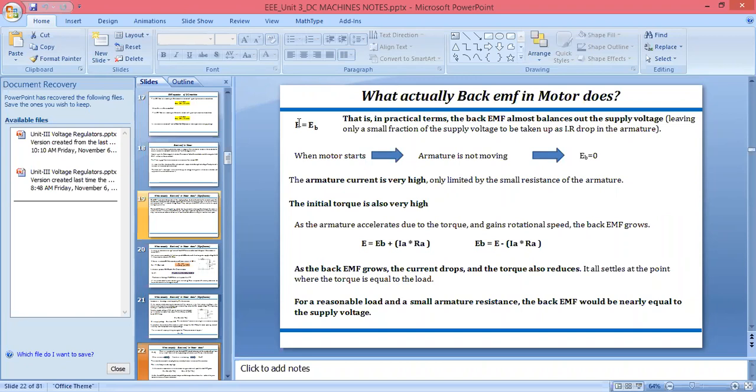If you see, when we are using the DC machine as a DC generator or a DC motor, the armature will be a rotor. It means the armature will behave as a conductor, it will rotate, it will carry current, and that current will lie in the magnetic field of the air gap, because we put the air gap there for cooling purposes. We have already seen these things in the construction of the DC machine.